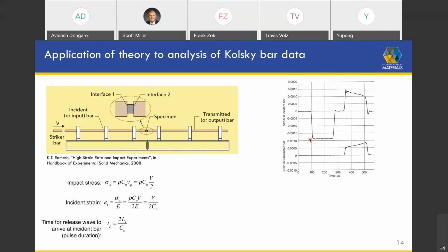When you get up to higher stresses, you find that dislocation motion itself, even by glide, depends on thermal energy. The more thermal energy you put into the system, the easier it is for dislocations to bypass obstacles in the lattice. So at the very low stresses, the material behaves essentially as a Newtonian material, where the stress is proportional to the strain rate.